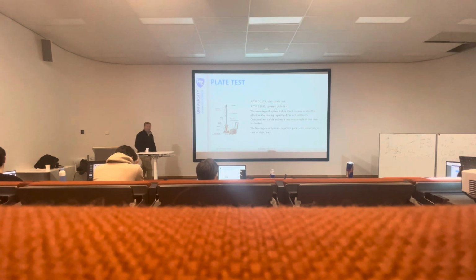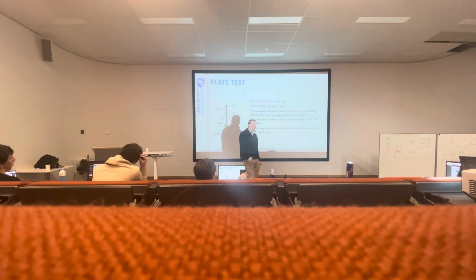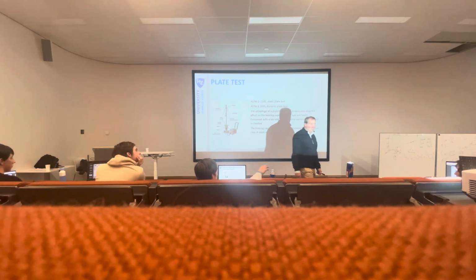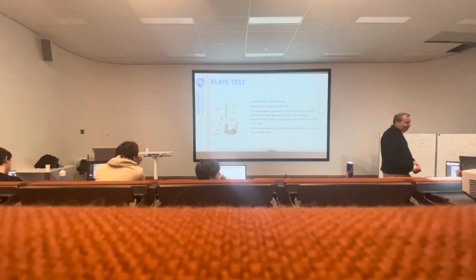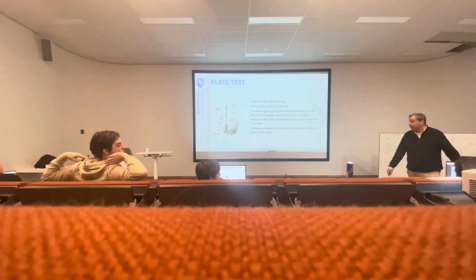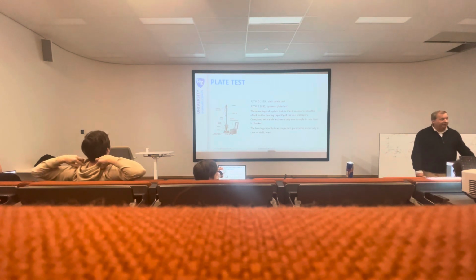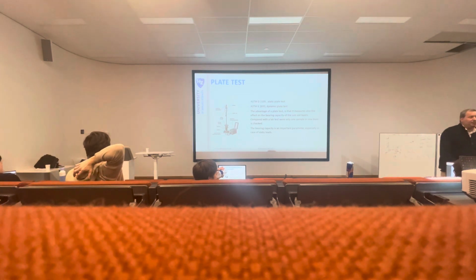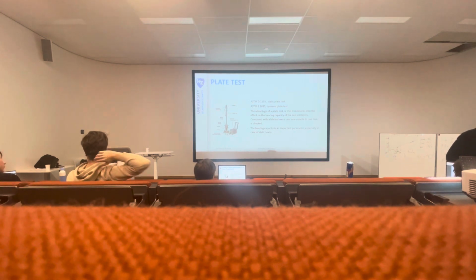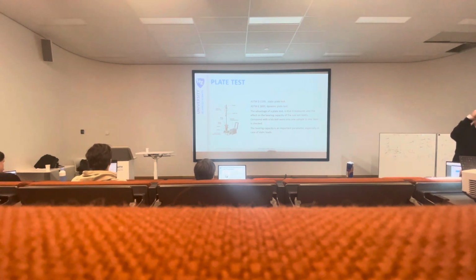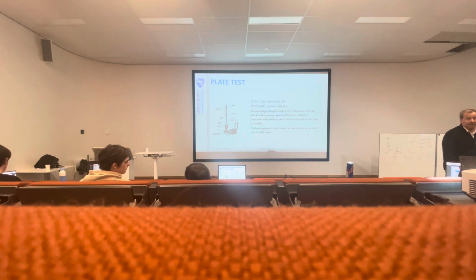A plate test. A plate test is a very complicated test. You have a plate and you push on it, you see the deflection, and that's it. Very complicated. So basically what we're going to do is EV1 and EV2 values, and that's something typical for the Germans. Before they start building the next layer on a pavement, they do an EV1 or EV2 test.